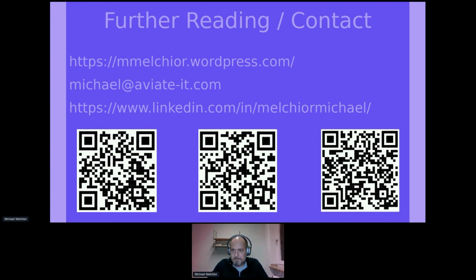EKF2, yes. Thing is, during that project, there was a major update of the PX4, and I rebased my project on that. And unfortunately, well, the memory on the F405 is very, very limited. And with the new update on PX4, the binary was a little bit too big, so it didn't fit on it. And I think I had to remove the EKF2, but I'm not that sure anymore. So best thing, Gonzalo, would be to have a look at the blog and at the GitHub repository.